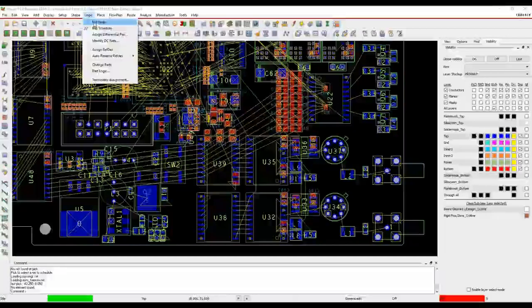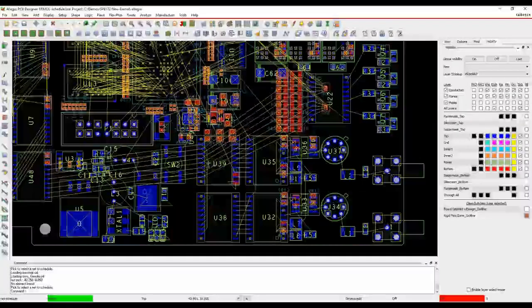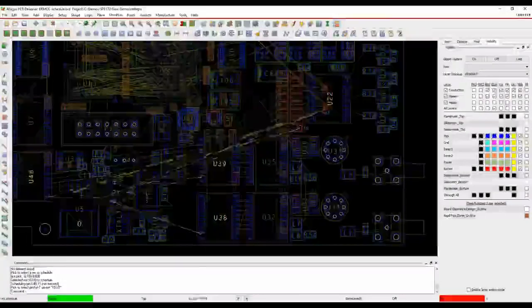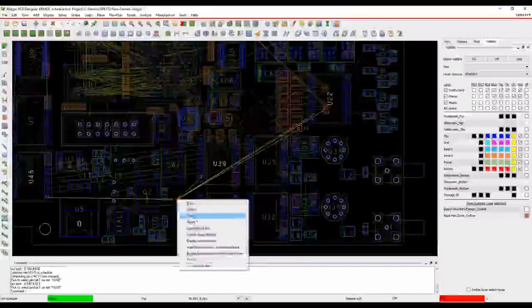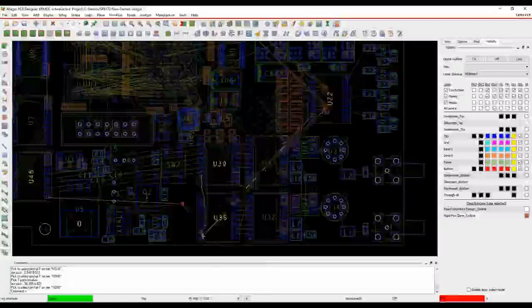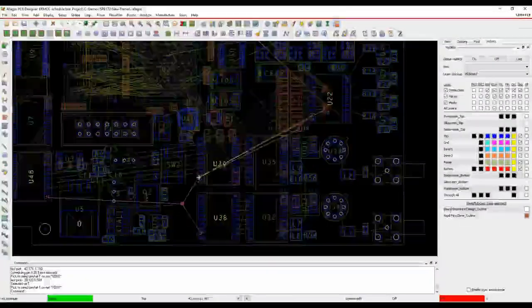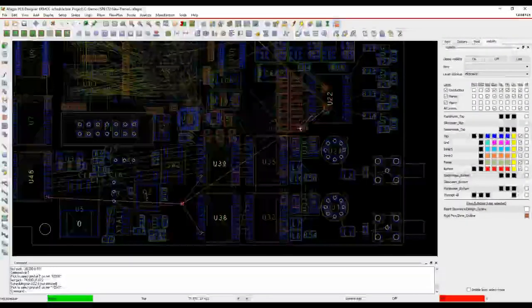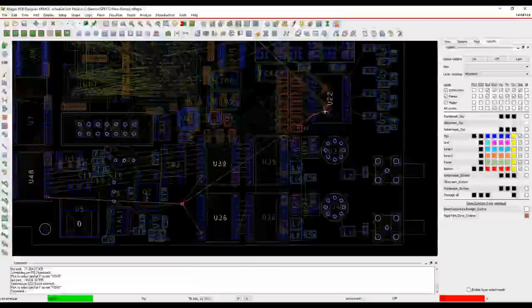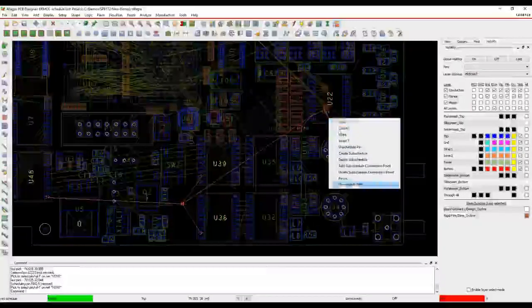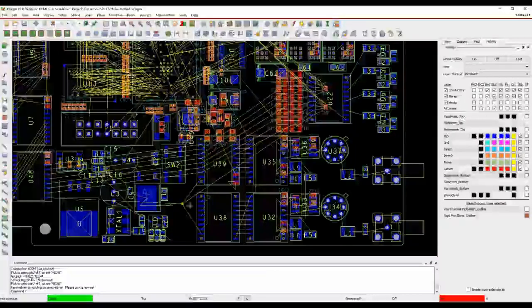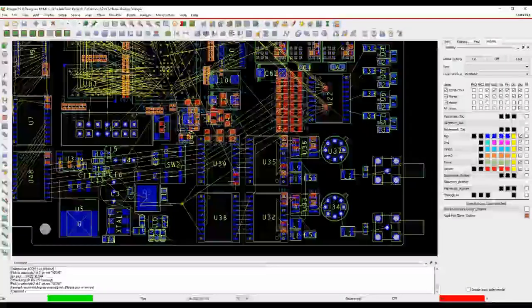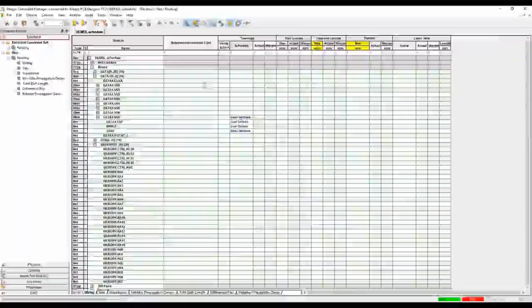We'll schedule a net. So we'll go to Logic and Net Schedule, and then we'll pick the net we want to schedule. I can start on this device, then insert a T-point, and then go to the device, back to the T-point, that device, back to the T-point, that device there, and then we'll go to the termination resistor, back to that device and the termination resistor there. When I finish that, my net has been scheduled and my T-point's been added. So we'll just finish the command.